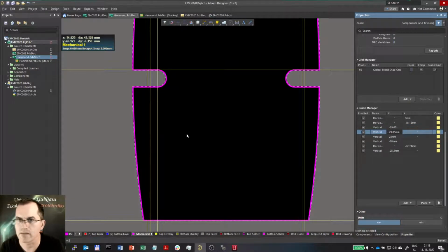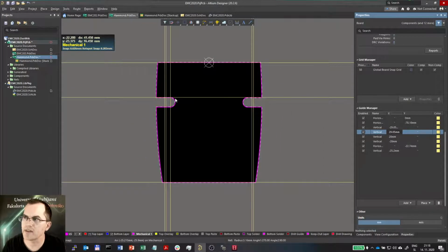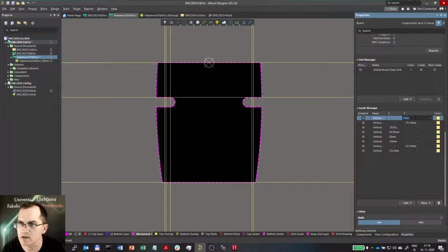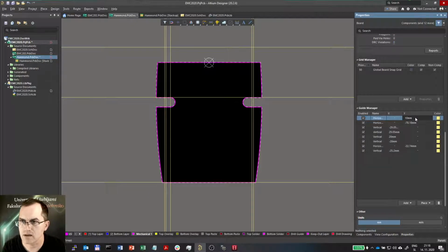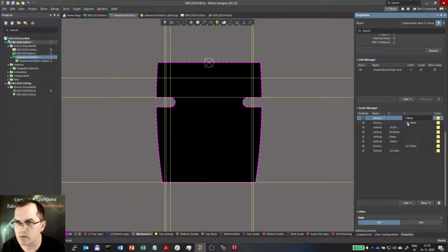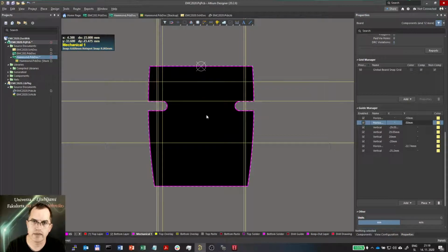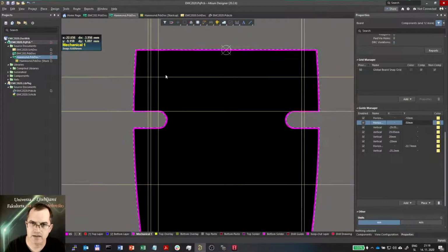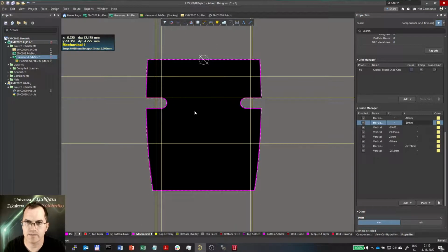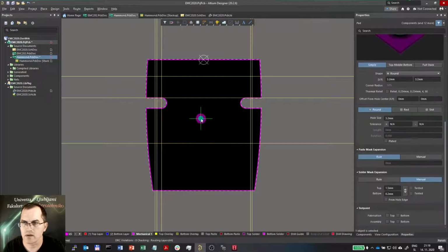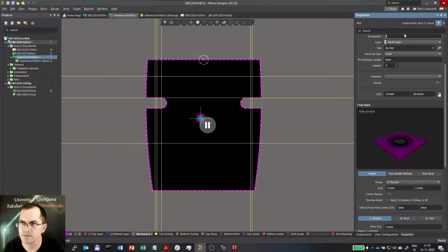29.05, right? Okay. So, and these holes are 40 millimeters apart vertically. So I will use maybe the top horizontal, and I will move it downwards for maybe 10 millimeters, minus 10 actually, but yeah. And the other one would be minus 50. Okay, I will put my pad here. Place pad. Okay, the pad should be defined.